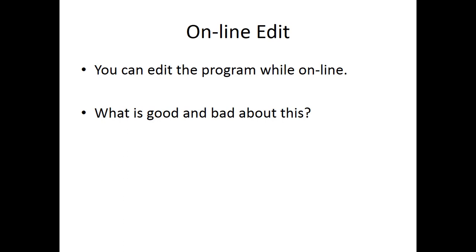You can just double click the rung when you're online, and then you can make some changes, change instruction types, for example, and then you could test your edits, compile your edits, and then assemble them, and then you can just do it online without going offline for quick edits. I don't mind doing some quick edits. If you're going to make substantial changes, you should probably do it offline.